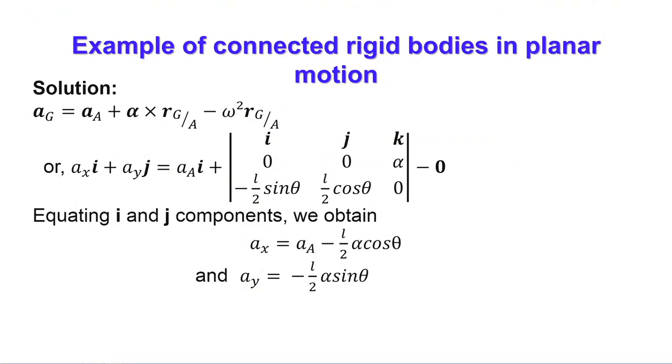So, a G equals a plus, so from one end we go to the other end, whose acceleration we know, then we know the two components, that means the radial acceleration component and the tangential component. A G is the acceleration of the center of mass, so that equals the acceleration vector of point A plus the angular acceleration, that is tangential acceleration, and radial acceleration.